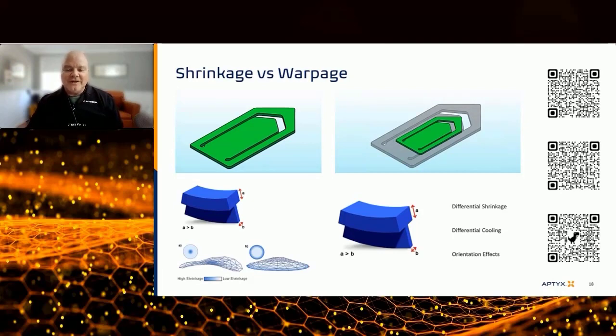And here I'm going to tie back to my schooling. I originally started as a civil engineer before I switched over to plastics. So I learned these shape properties and how they can influence stiffness and calculating mass, center of mass, moment of inertia, and this neutral axis. So if you apply a load to this shape, it's going to bend and the stresses are going to balance along this theoretical axis. And in this case, the load is shrinkage. And so if you're thick and you shrink more than thin on the bottom, you're going to create this kind of pinch on the top. And it's going to shrink less on the bottom, and so you'll get this shape factor.